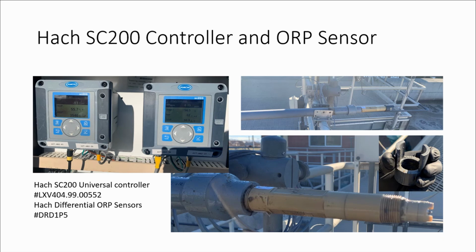The operators love it because it's really intuitive for the menus for calibration for all the probes, no matter what. They're self-identifying, so when you plug a probe into it, it knows what probe you plugged into it, so that it loads that program off the probe to it. Okay. So really nice, really easy use. And then on the right, you see the actual ORP probe out of the water.